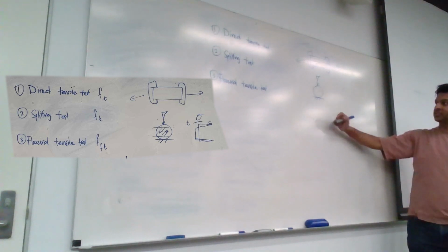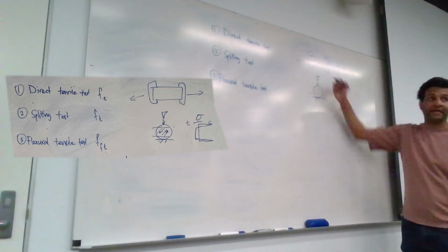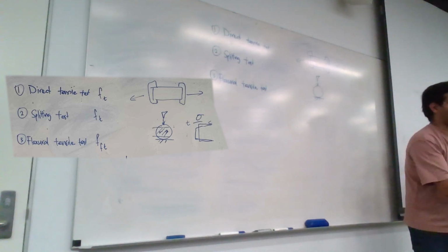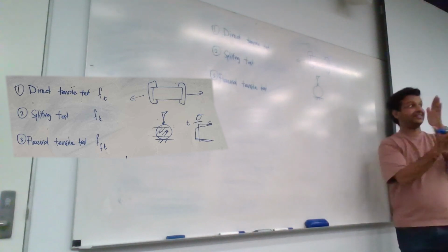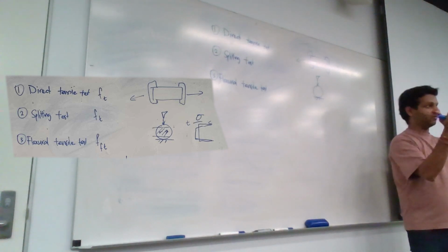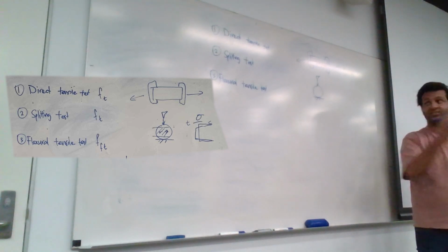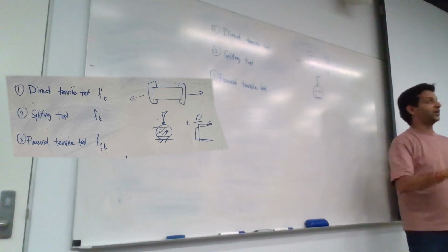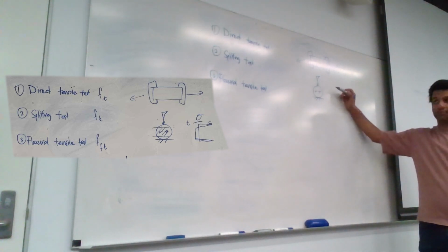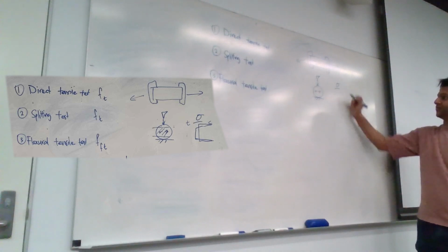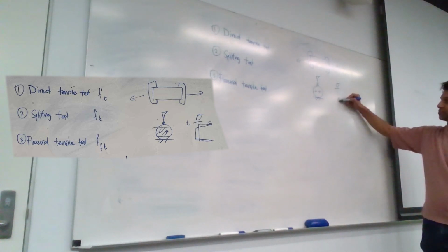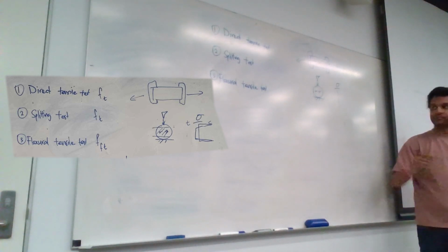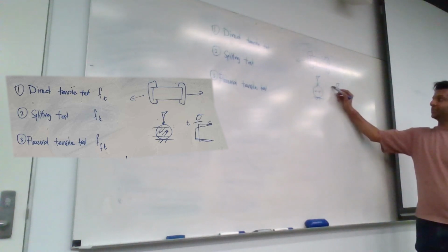It's because if you have a blade like this with a sharp edge and you're slicing it through, it's inducing a stress that causes it to split, right? For it to split, there has to be a tensile stress pulling it apart that way. Okay? If you want to know exactly what the stress distribution looks like, if I sketch out the stress distribution, that's your straight line, right? Your profile. Let's say this side is compression, this side is tension.